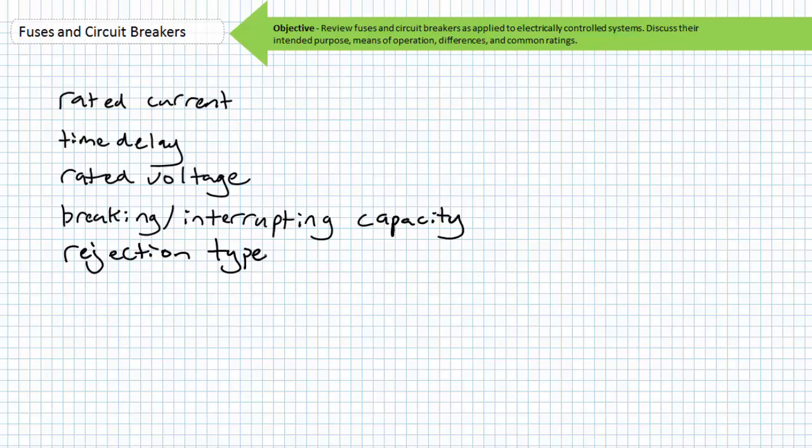Recall that motors can exhibit a phenomenon called inrush current, in which an intense but brief draw of current occurs when the motor is first started. Inrush current can sometimes be in excess of 6 times regular operating current. A slow blow fuse is often used in series with a motor supply voltage by allowing the temporary passage of such high current, but sensing sustained current draw, the fuse blows after a predetermined time.